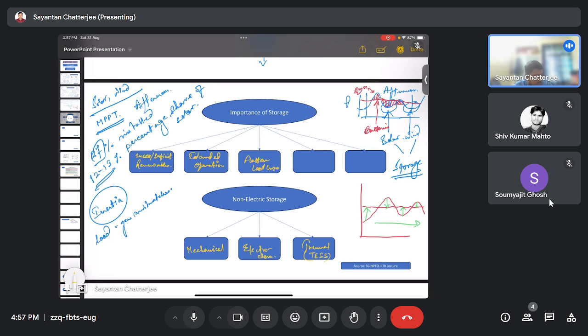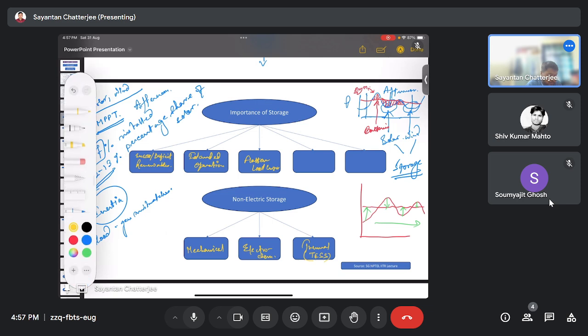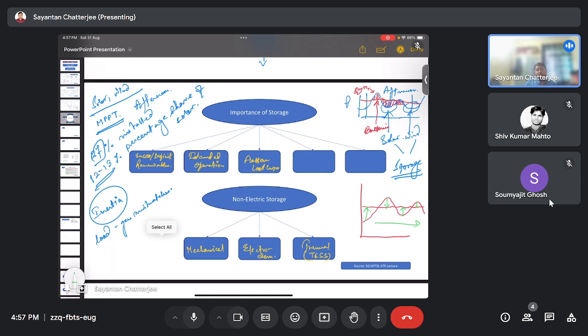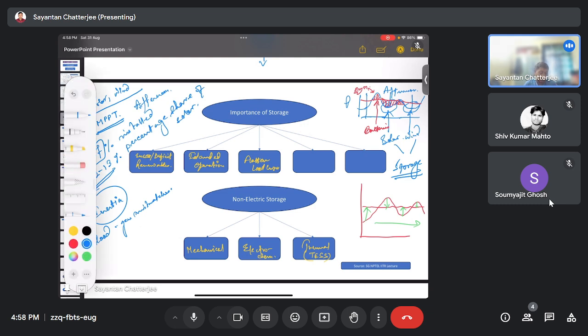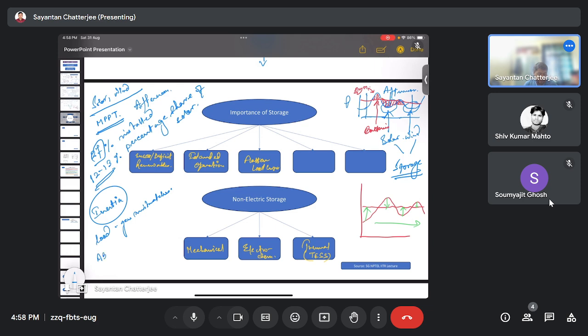So already we have discussed the function of pump storage plants. During the valleys, we can store the excess amount of energy by pumping the water from the lower dam to the upper dam, and during the evening peak period, we can switch on these power plants. The major aim is to maintain the frequency, and these power plants get ABT, if you are aware of the term, that is availability based tariffs.